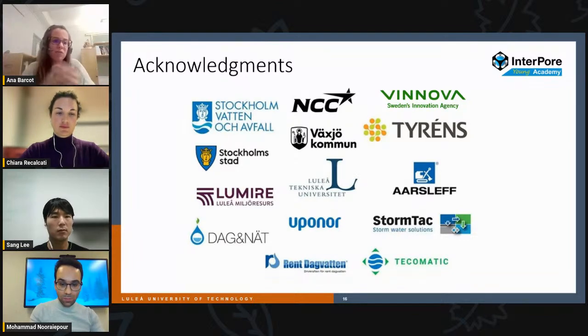Here, for example, as I already said, around trees, around lampposts. It is intended for applications where space is limited, and especially in urbanized areas this is a huge problem. We believe that this kind of solution would relieve a lot of stress on the existing drainage systems, because it would definitely help in reducing the floods and runoff volumes in such limited areas.